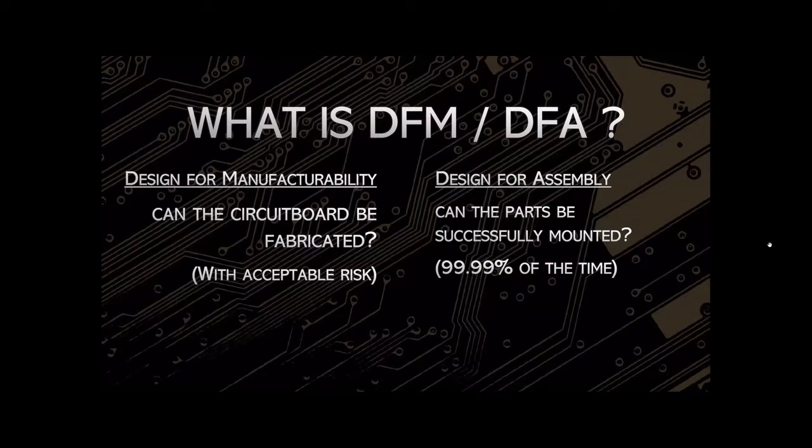And then there's DFA, which is design for assembly. As the name suggests, we're now focusing on the layout of the components that are going to be placed on the circuit board during assembly. And by running these DFA checks, we can answer the question, can the parts be successfully mounted? And although there's a high probability of success at this point, a mistake can be expensive for the customer and for the assembly house.